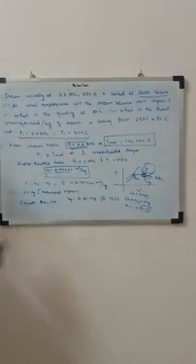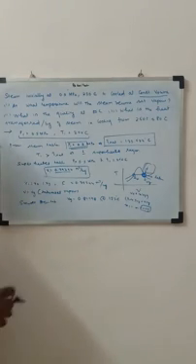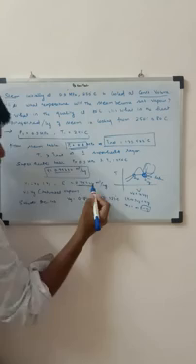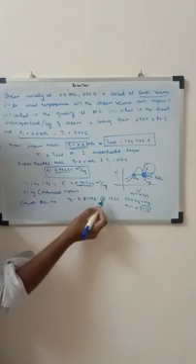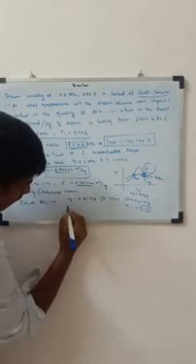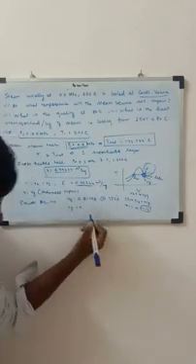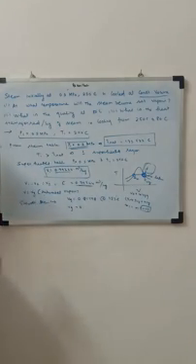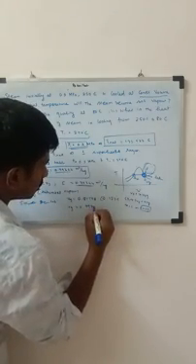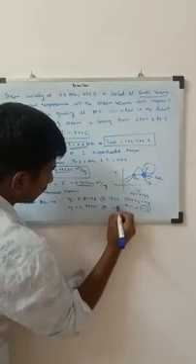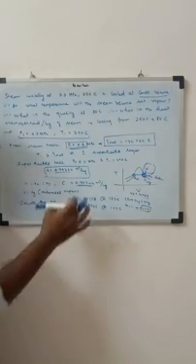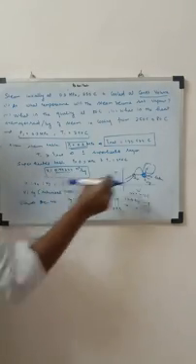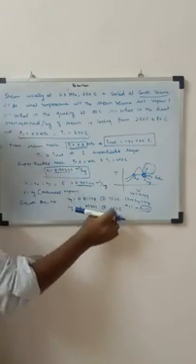So I have this pressure, I go through the steam table, and I am trying to find the value that is near to this. My Vg value is 0.81598 when the temperature is 123, and my Vg value is 0.79261 at 124 degrees. So my Vg value is somewhere in between these two. The temperature at which it becomes saturated vapor will be somewhere in between these two.